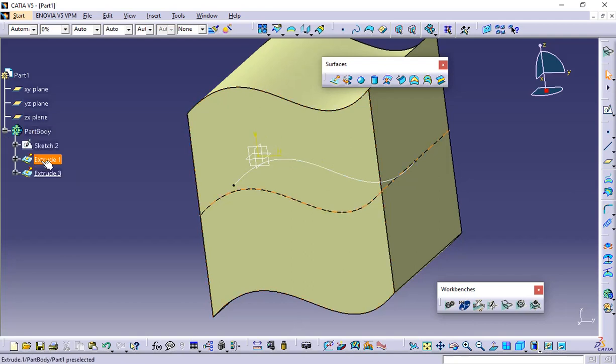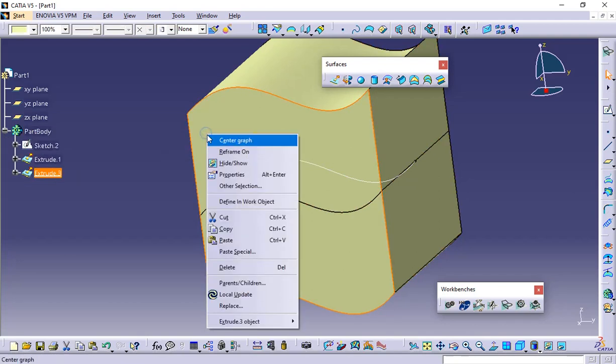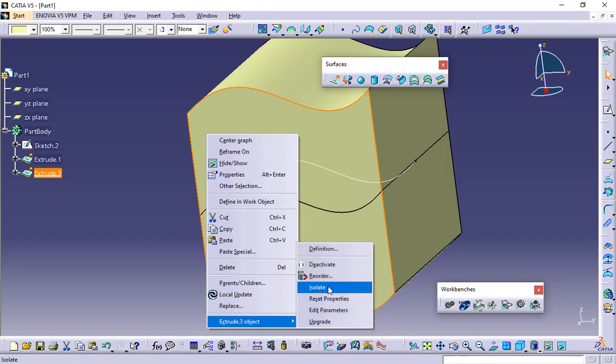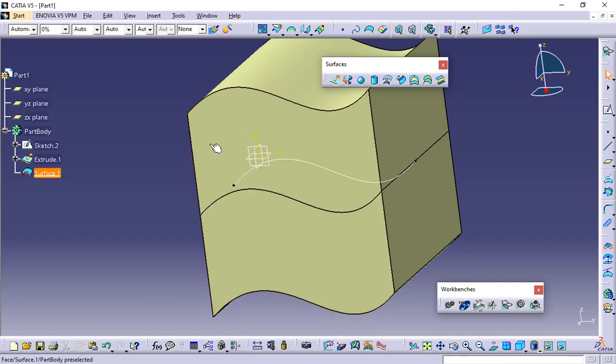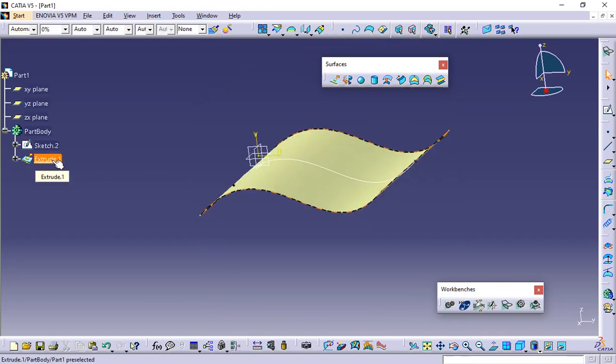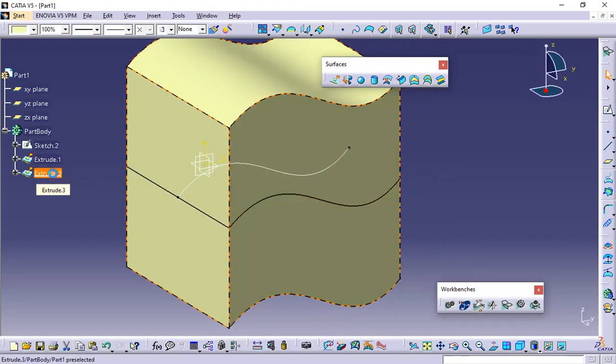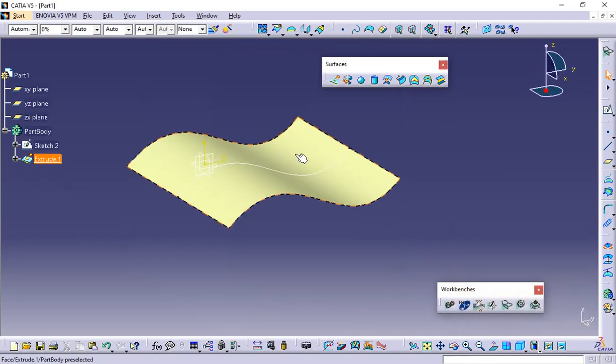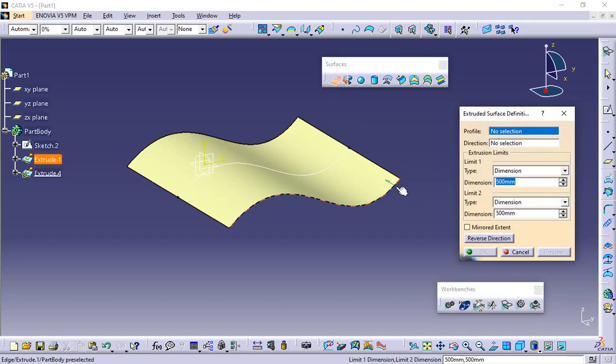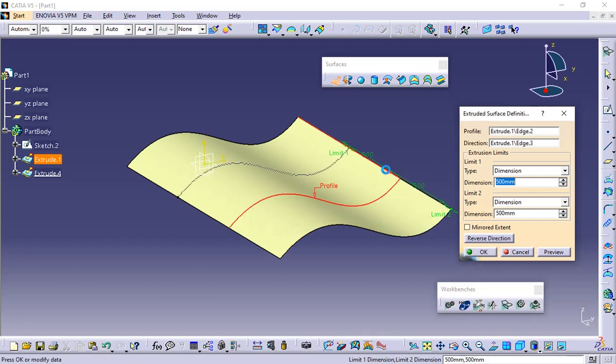And so do this isolate option. So this surface has been isolated. So I'm deleting the surface. Same thing happened. So this is how it works when you select the whole profile. When I select this one, all the four sets got selected at a time and they were extruded using this extrude option. So again I'm using the extrude option and selecting the edges individually.